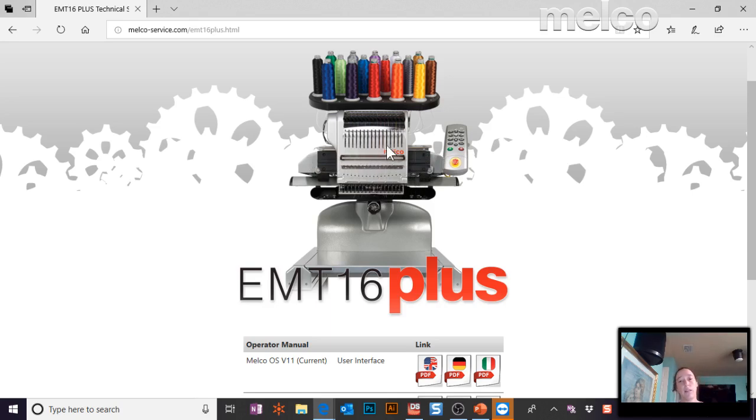You'll grease the presser foot and the cam on the back of the cam. When that's done, you've got to put this cover back on. If you do not put this cover on, when the machine goes to index the needle case over, as it's moving over, needle 1 will fall, needle 2 will fall, needle 3, it'll keep on falling because all your needle bars are being held up by this cover.